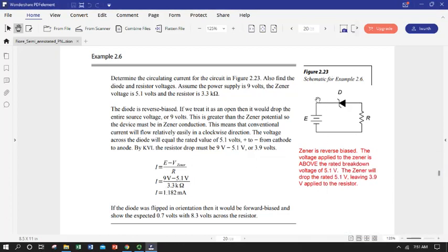In reality, what I would typically use this for would be to use the voltage drop over this Zener as the literal voltage supply for something that I needed to be very stable DC. No ripple like we have with a rectifier, which is something we'll learn about later. This is a very consistent DC. So that's a good way of breaking up the voltage in a circuit as an alternative to just a resistor voltage divider.